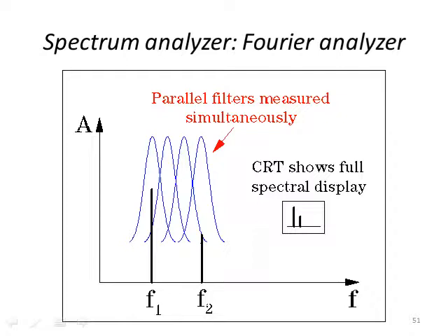So if your signal has multiple frequency content, let's say you have, in this case, a signal that has two sine signals that are modulated together, this instrument will go through this particular signal, and obviously there's a digital signal processor in the system too, and it can determine if the amplitude at a particular frequency is high at particular frequency locations by doing this filtering, very, very sharp filtering.